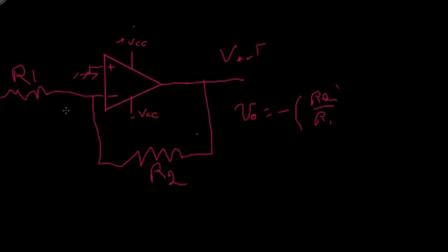Now again, we went through and looked at the characteristics of this amplifier. It's useful for me to think of this point as being a node. So when I apply V in, we'll make the leap of faith that the open loop gain of this op amp is operating in such a way that it's going to seek to maintain V minus and V plus at the same potential. Notice that the positive input terminal is grounded, so I'm looking for 0 volts.